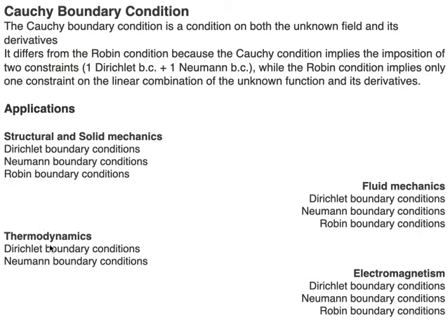In thermodynamics, Dirichlet boundary conditions consist of surfaces, that is, in 3D problems, held at fixed temperatures. Neumann boundary conditions in thermodynamics represent the heat flux across the boundaries, and a perfect insulator reflects a homogeneous condition which is naturally satisfied. All warmed and cooled boundaries are required to have boundary conditions explicitly assigned. This is normally the case with electronic components or an external cooling spray or channel, for example.